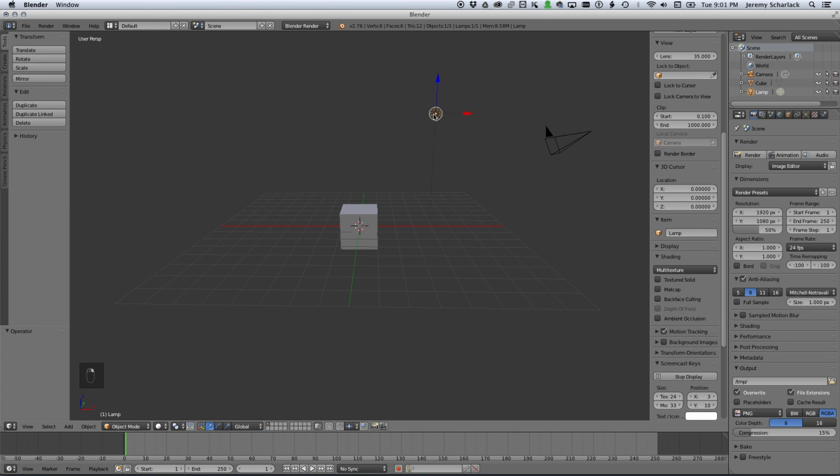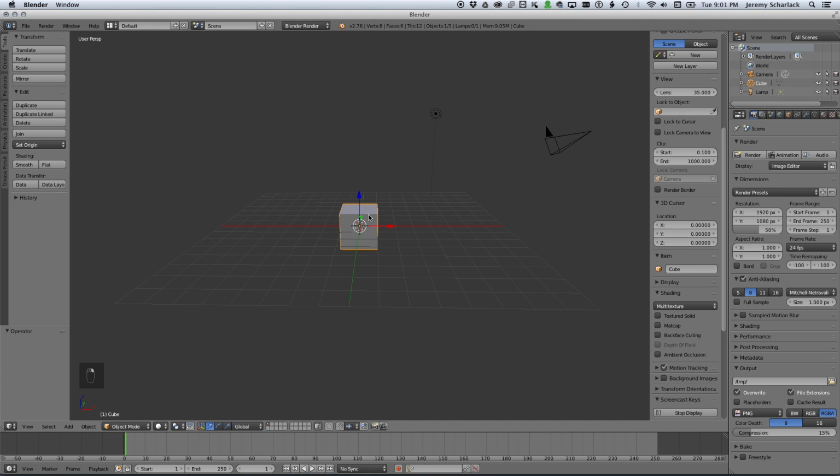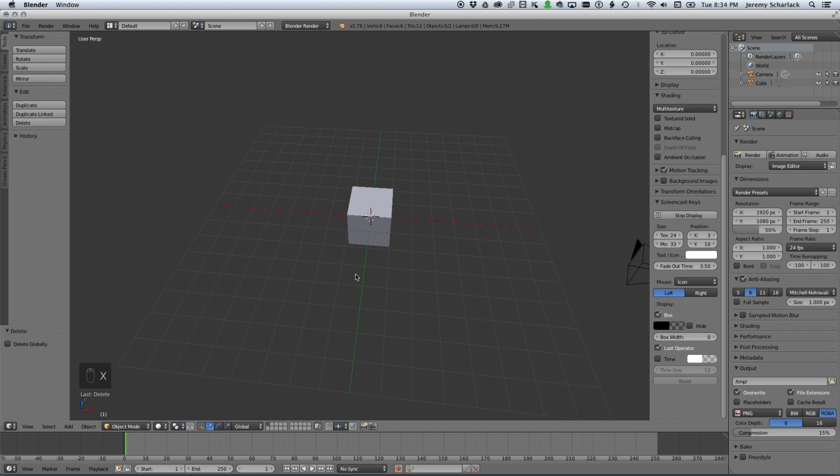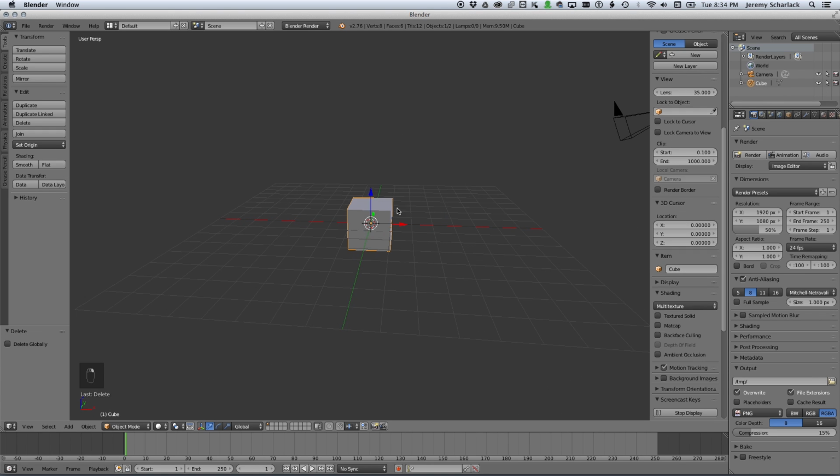And what I just selected here is a light. This is the camera. And this is the default cube. And I'm going to get rid of the light. You hit X to delete it. And I'm going to grab the default cube. And since we're going to turn that into our box, I'm going to call it a box. And we'll just leave the camera there for now.